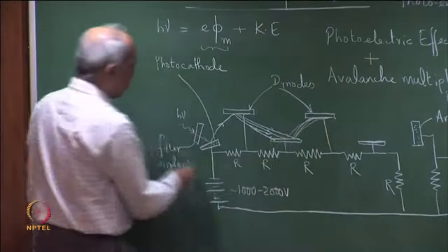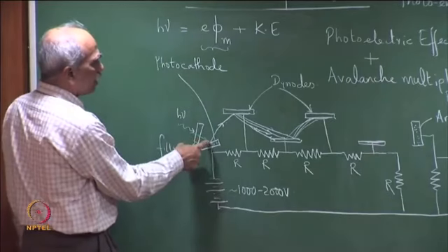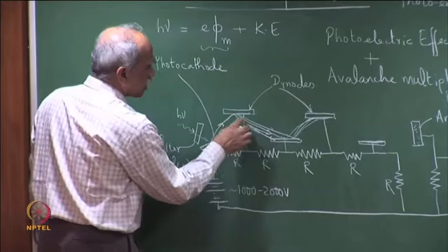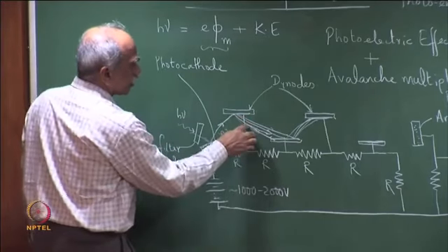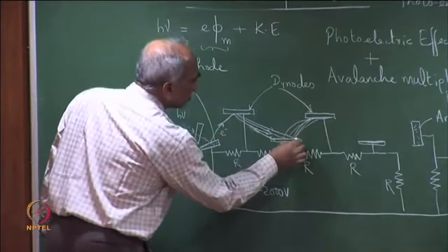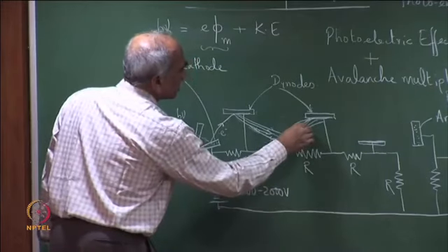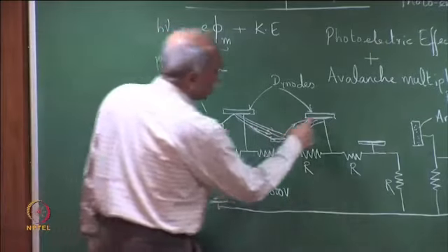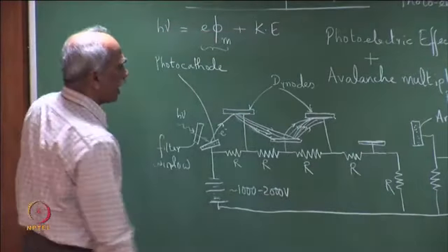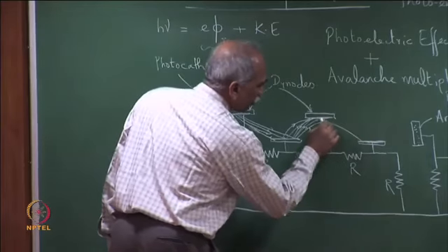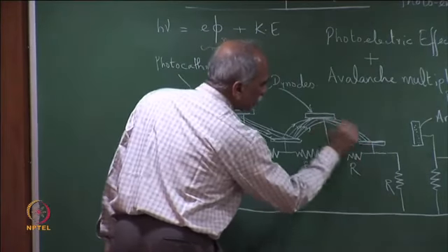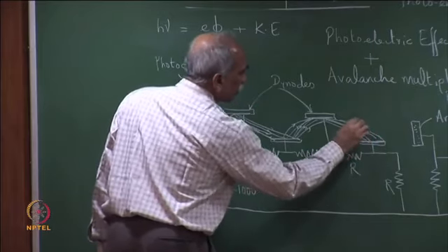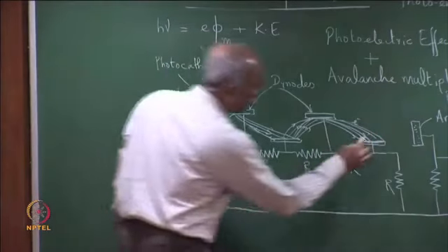So, we started with one photon incident releasing one electron, which in turn releases further electrons, leading to more and more electrons, and this kind of avalanche process takes place. Depending on the number of dynodes, an avalanche takes place. So, let me illustrate further that the avalanche is taking place. These are all electrons released, which are finally collected.